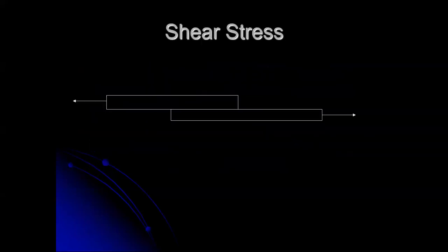So let's get a basic visualization here for what shear stresses are. Let's take a look at what's on the screen. We've got two plates, and they are lapped over each other. Those of you who have done our sheet metal course are familiar with this. This is a lap joint. Typically, you drill some number of holes and install some number of rivets, possibly multiple rows, to hold those two together. But there are lots of ways of fighting against the shear stresses.